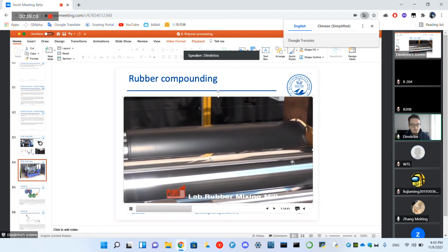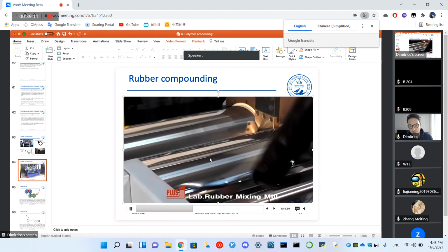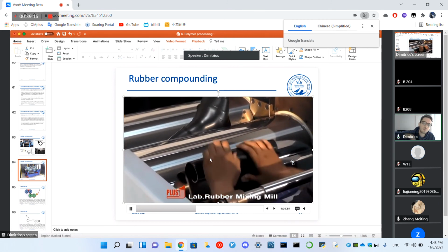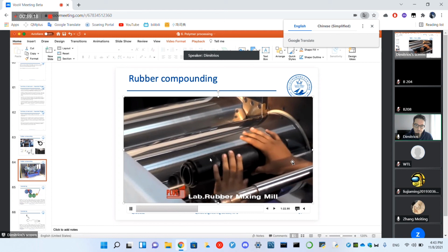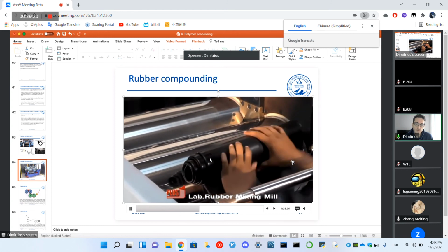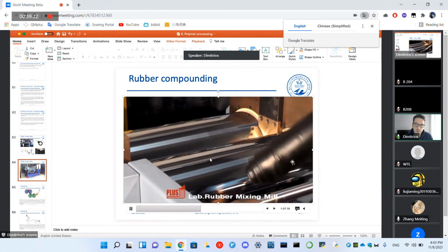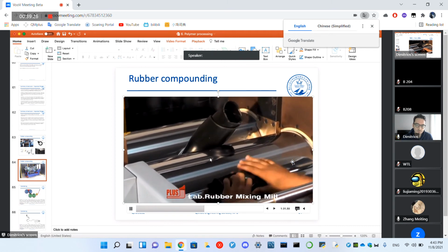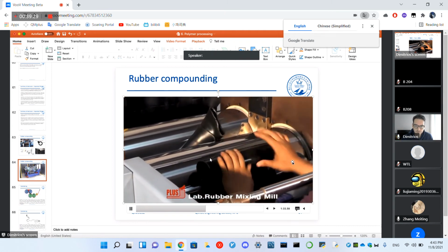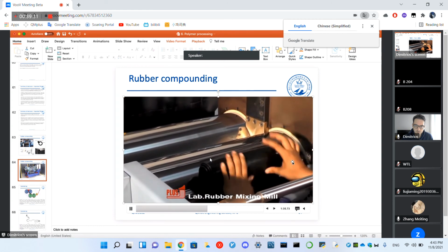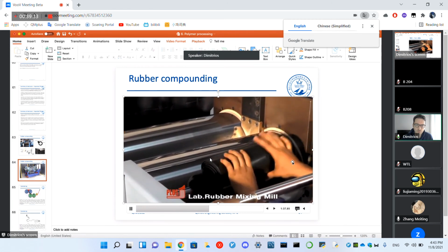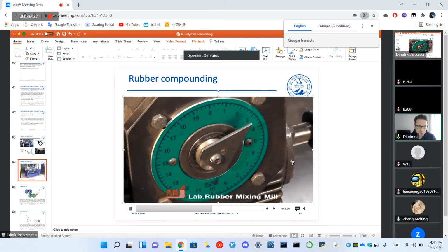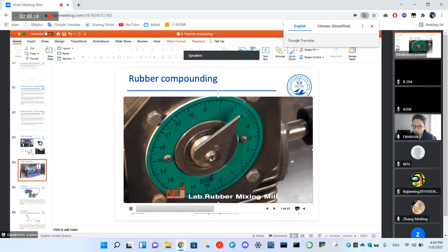You see how smooth it becomes, and then we cut it and we put it again over there, you see, in order to ensure that mixing is effective, okay? So we roll it and then we feed it again between the rolls. Because of sulfur, generally, all rubber processing plants do not smell very good. So it's a very bad smell when processing rubber.